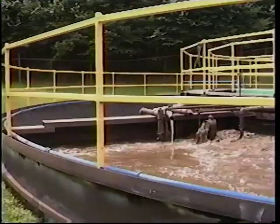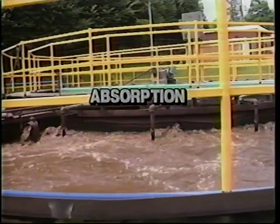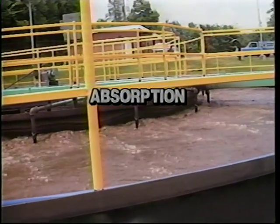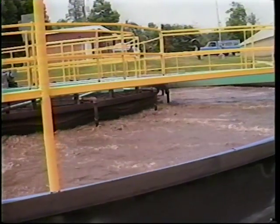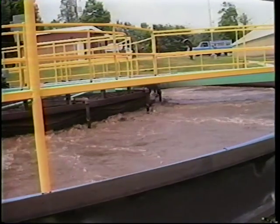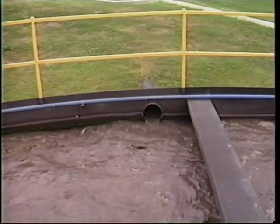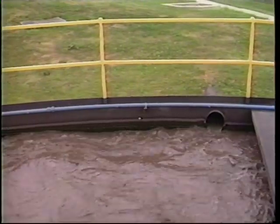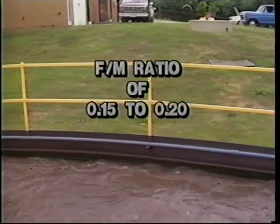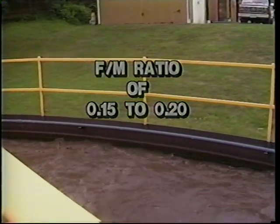It is returned to the re-aeration tank where a process known as absorption takes place as the hungry microorganisms consume the food they snatched in the contact tank. The detention time in the re-aeration tank is usually 1 to 4 hours. The activated sludge mixed liquor then flows from the re-aeration tank back into the contact tank where the whole process starts over again. The typical F to M ratio for the contact stabilization process is 0.15 to 0.20.